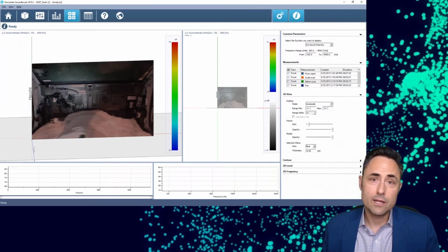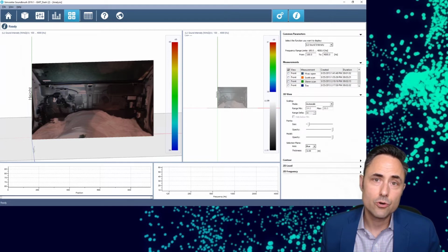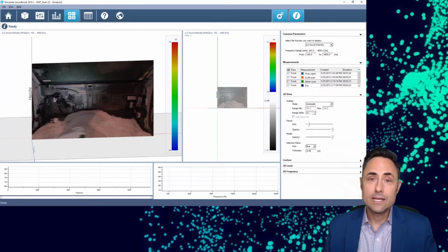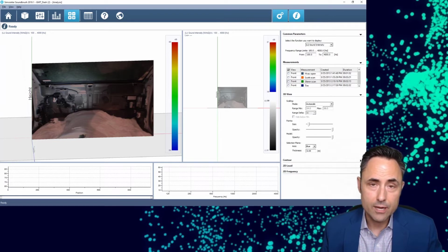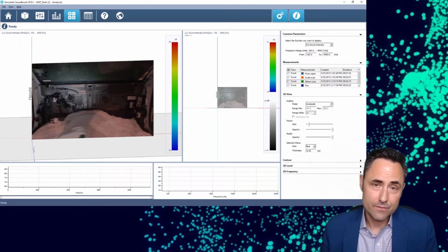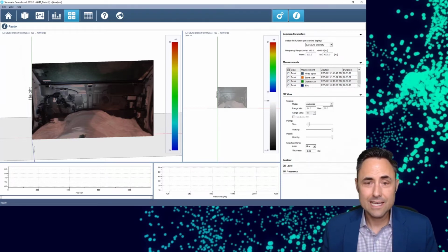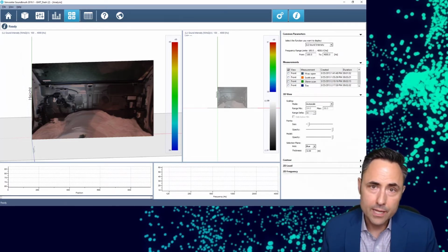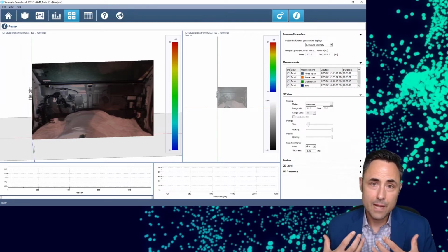And part of what is really important in the interior noise level of an automobile is controlling how much sound gets through that front of dash, right? We might have an engine or a motor up there, and we want to keep the sound on the far side and out of the passenger cabin. And so to test this, we can put a broadband frequency source that's really loud in that front compartment and then measure the sound on the passenger side of that front of dash, right?